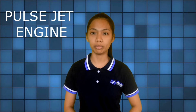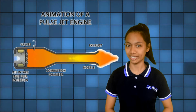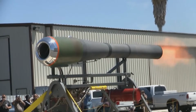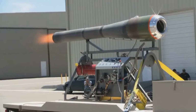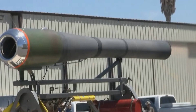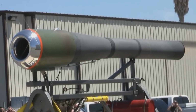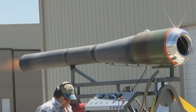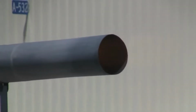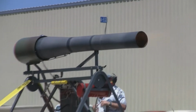The pulse jet engine is one of the earliest air-breathing reaction engines. It is a type of engine in which the combustion occurs in pulses, and this is how it works. The fuel is sprayed into the combustion chamber and ignited. The heated air expands and closes the one-way shutter valve at the front of the combustion chamber and exits through the open nozzle at the rear. As soon as the pressure inside the combustion chamber decreases, the shutters open and the air flows in, mixes with the fuel and is ignited. Thrust is produced in a series of pulses, and the sound produced by the pulse jet-powered missiles used during World War II caused them to be called buzz bombs.